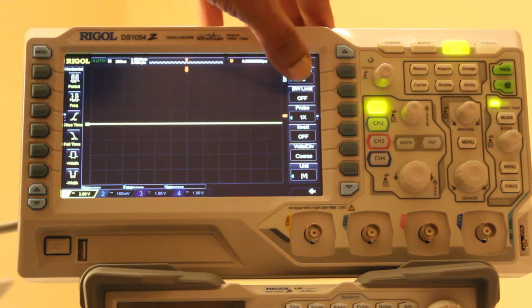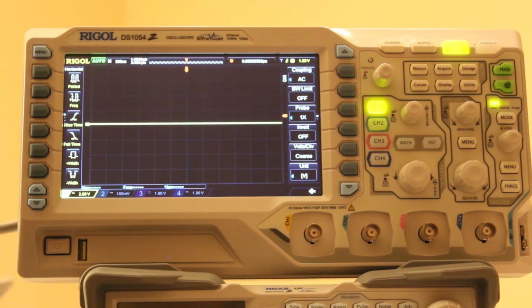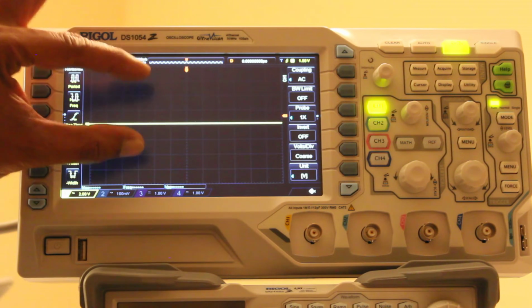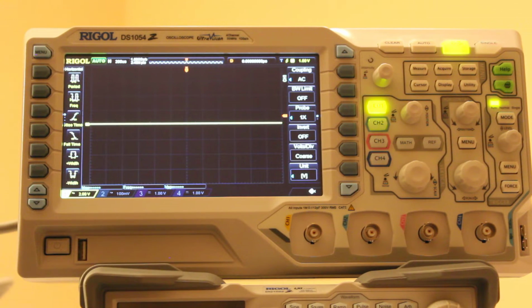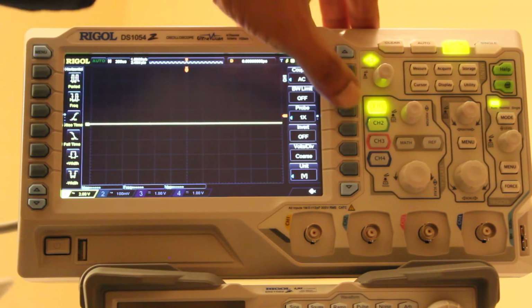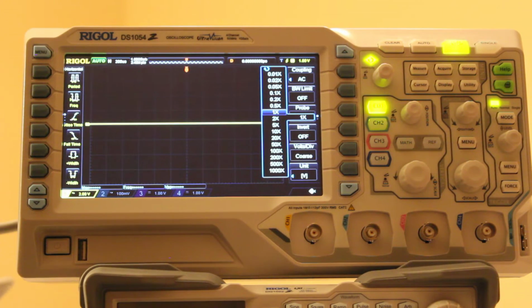And right now we also have something called the probe. Probe is set to 1x. So whatever the signal coming in, the measurement is a 1-to-1 ratio. So if it's a 10 volts peak to peak signal coming in, then we will see 10 volts measured. We can change the probe setting to 10x, 20x, 2x, 5x, up to 1000 times. So if there is a very small voltage, I can multiply it by 200 times to fit into the screen and see it nicely.